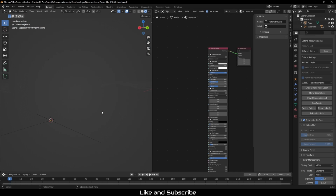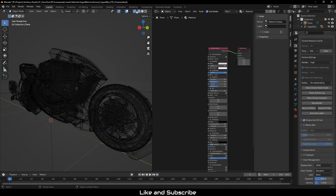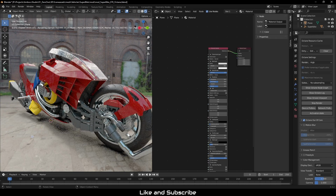This also means that we have to manage the memory usage of our scene. We have to be careful on the textures we use, especially the sizes, and we need to be careful with our geometry. If we have geometry that's not going to be seen, it should be removed. And we should also use as much instancing as possible.